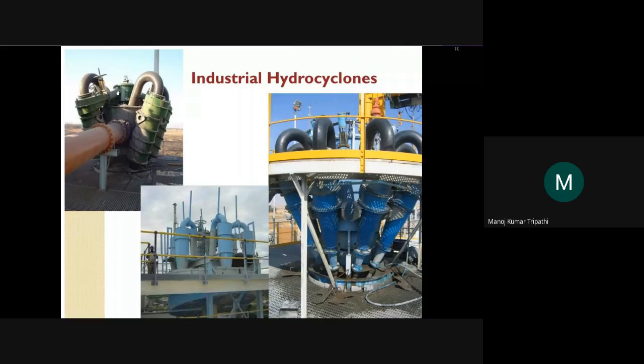And this pipe that you are seeing here, if you can see the hand tool here, that pipe is the inlet for the cyclone. It is off centered at one end of this circular top cross section. This is not directing the flow at a diameter of this circular cross section. This is slightly off centered, so that there is a rotating motion of the particles as well as fluid.